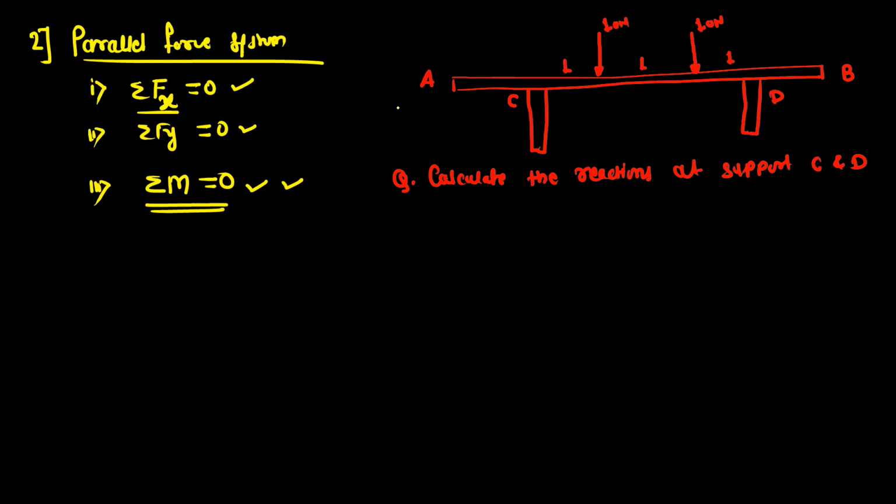Okay, so your first step when we solve problems on equilibrium, whether it is a concurrent force system or a parallel force system, is to draw the free body diagram. By the free body diagram, you can visualize all the forces and reactions on the system. So just isolate the rod AB, because the rod AB is subjected to reactions and forces.